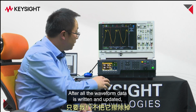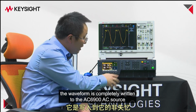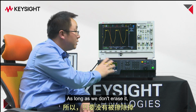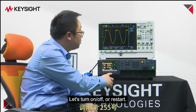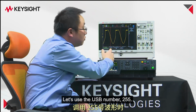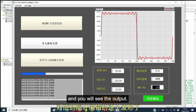After all the waveform data is written and updated, the waveform is completely written to the AC6900 AC source in the corresponding waveform library. As long as we don't erase it, it is written to its non-volatile memory in the system files. Let's turn it off or restart. Let's use the ARB number 255. In this case, the waveform of number 255 was just written, and you will see the output. The waveform is now edited.